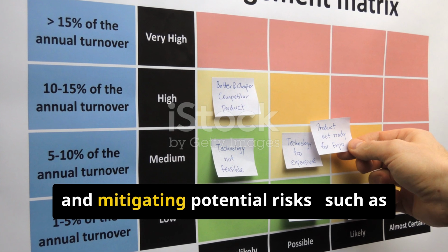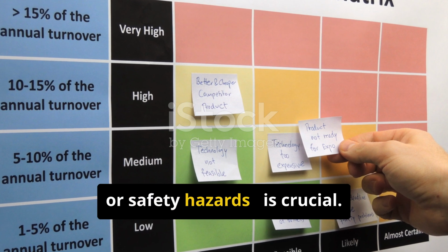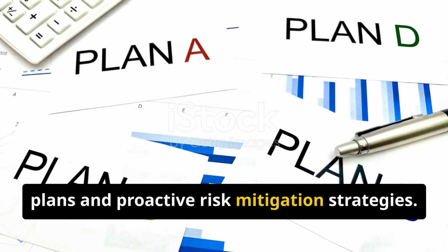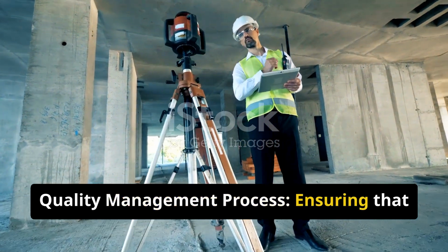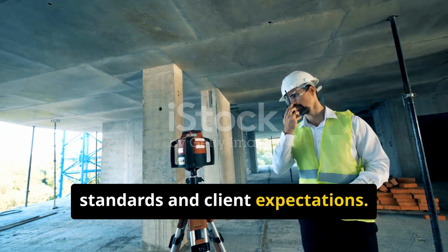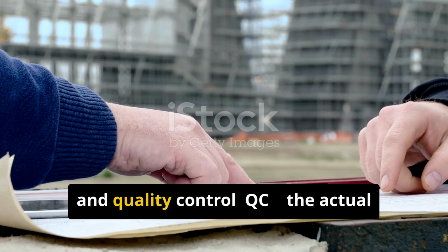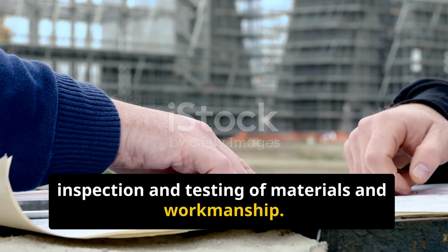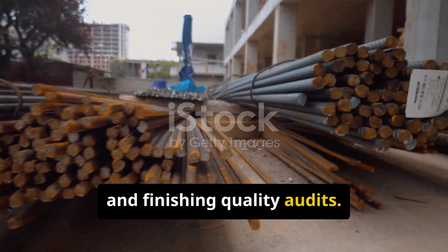2. Risk management process. Identifying, assessing, and mitigating potential risks, such as budget overruns, material shortages, or safety hazards, is crucial. This involves developing contingency plans and proactive risk mitigation strategies. 3. Quality management process. Ensuring that the construction meets specified quality standards and client expectations. This includes quality assurance, QA, planning for quality and quality control, QC, the actual inspection and testing of materials and workmanship. Think material testing, structural integrity checks, and finishing quality audits.